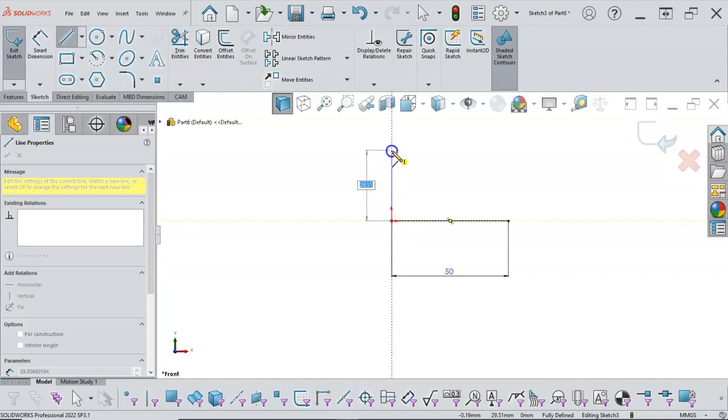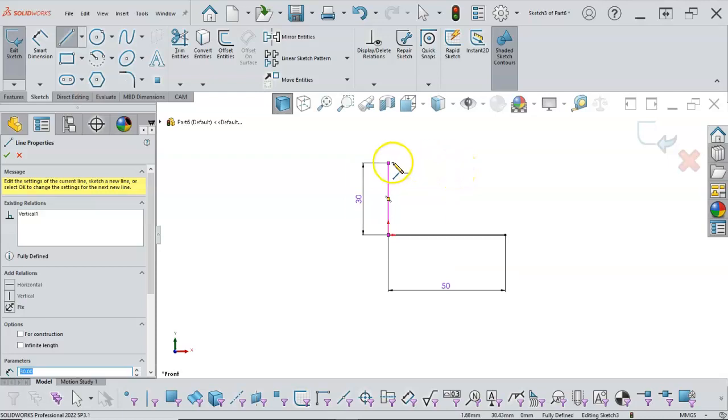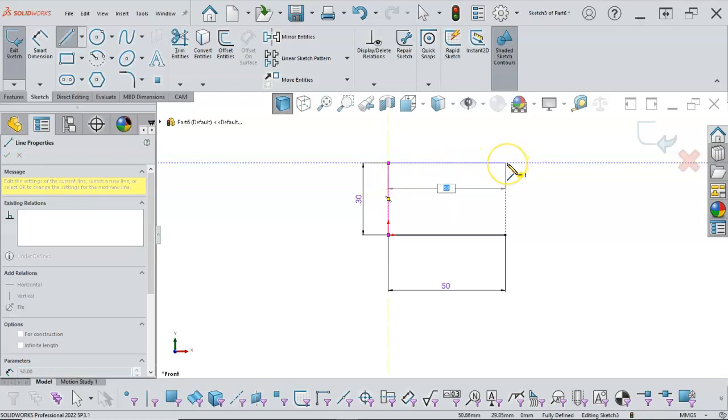So I'm doing click drag, and I'm still holding down the left mouse button. So if I want this to be 30 millimeters and enter, as soon as I hit enter, it's ready to go. And if we go click, click, I can click on the start and drag it out. And the importance of turning on that create the dimension only if the value is entered is I've got my inference lines.